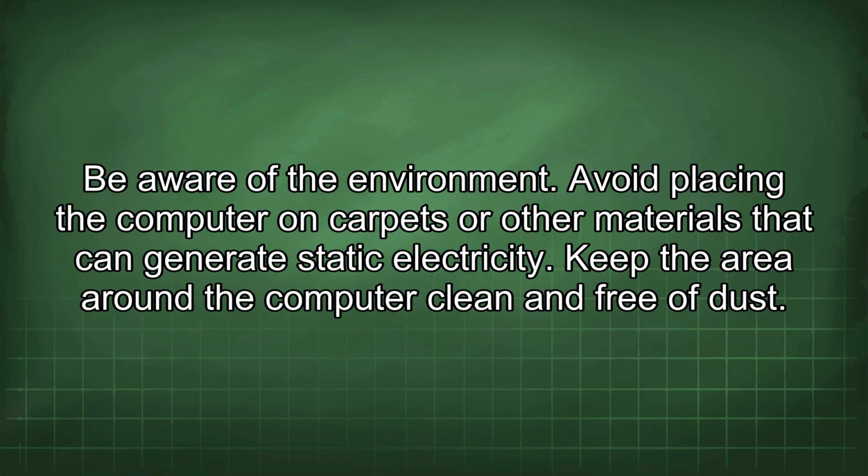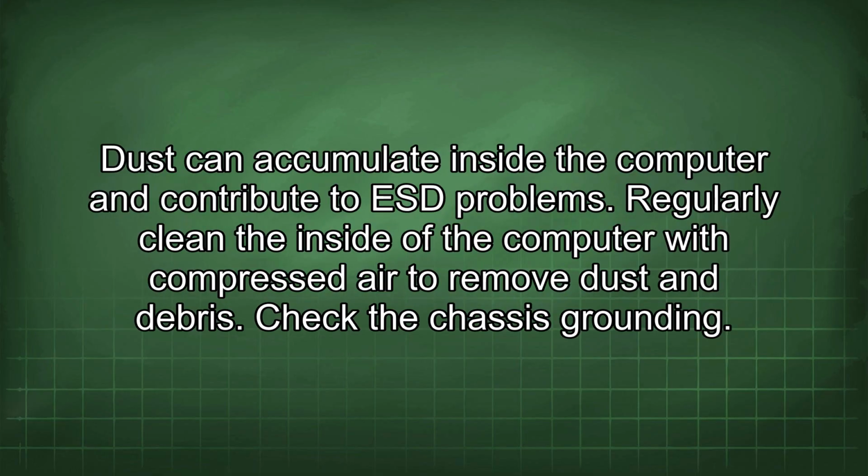Be aware of the environment. Avoid placing the computer on carpets or other materials that can generate static electricity. Keep the area around the computer clean and free of dust. Dust can accumulate inside the computer and contribute to ESD problems. Regularly clean the inside of the computer with compressed air to remove dust and debris.